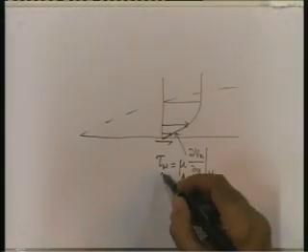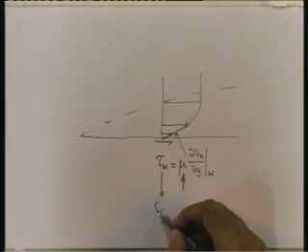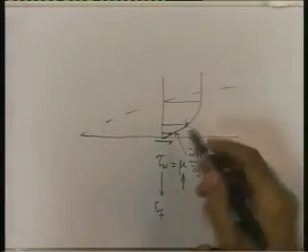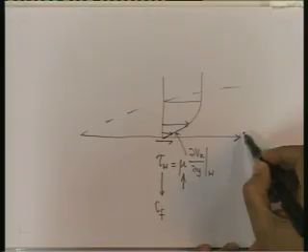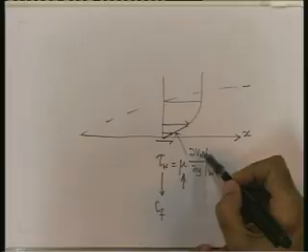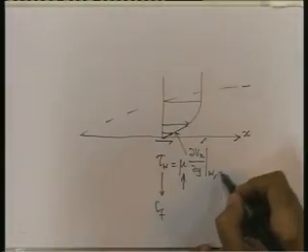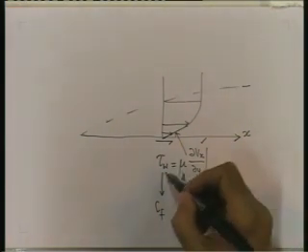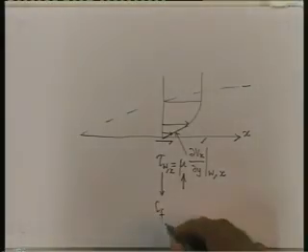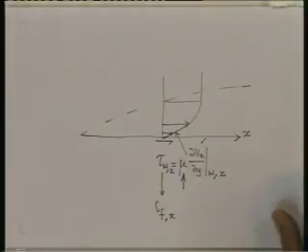And this tau is converted into the dimensionless drag coefficient or skin friction coefficient. As we go along the length of the plate, the boundary layer thickness varies, so the gradient at the wall varies. This will be different at different values of x, hence the shear stress will be different at different values of x, and hence the drag coefficient will be different at different values of x.